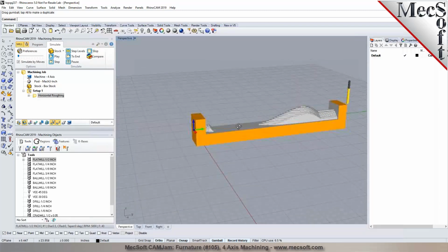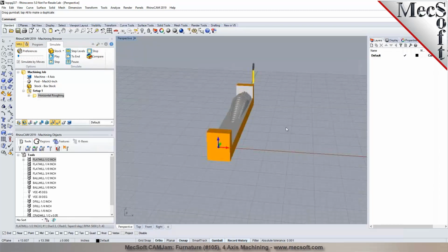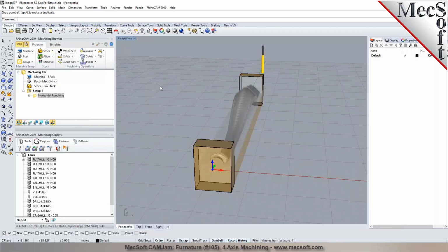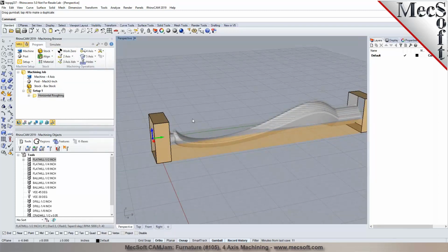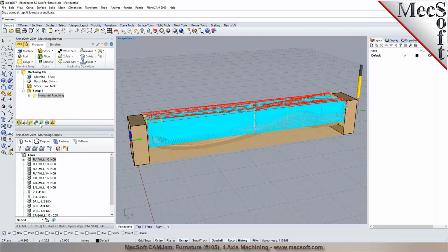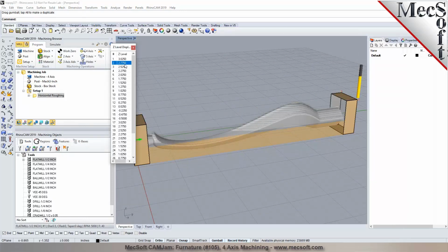Okay. That's in a 3-axis setup. So your table stays at 0 degrees, and then you're programming roughing in levels. So this is a very efficient way to rough it down in levels, because you're just locking the rotary axis and then you're programming it.